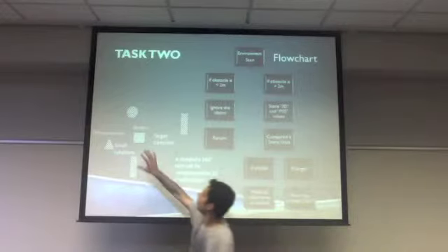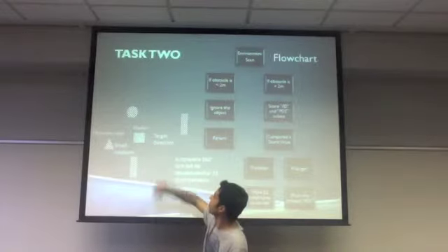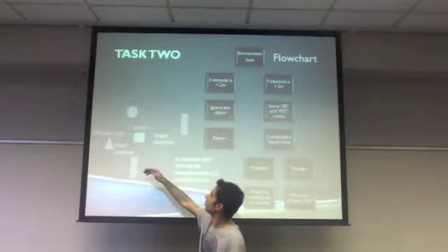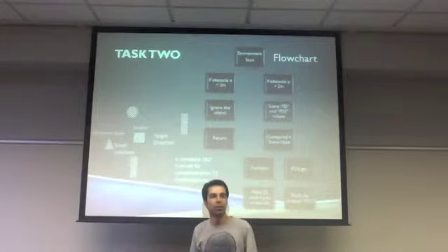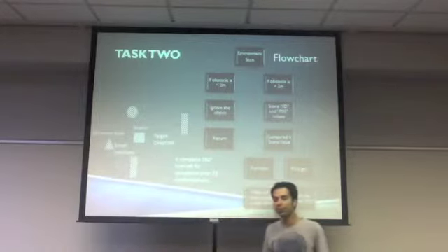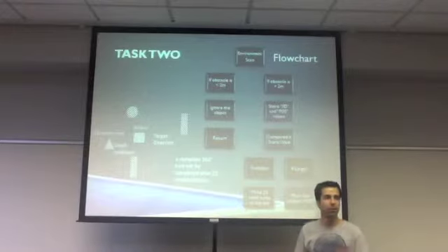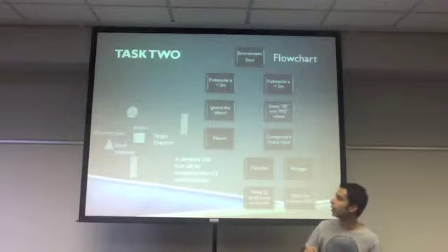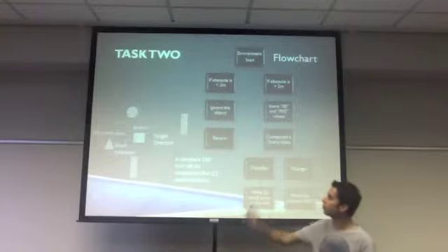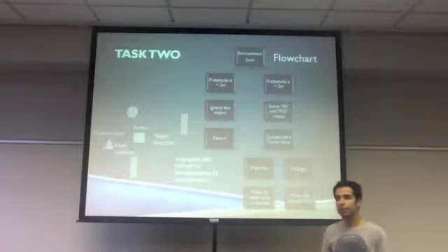We put the robot in the middle of the workspace and wrote a code to make the robot do small steps, and at each step measure the distance of the object from it and compare it with the previous distances. This way, by making a whole circle, it can find the furthest object, and finally it can align itself to the target and move toward it. In the next slide, we are going to see the video of the robot in action.